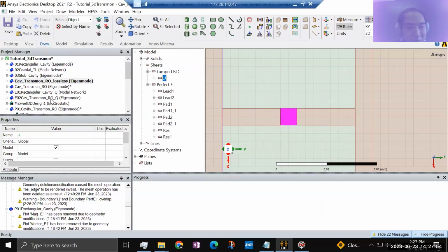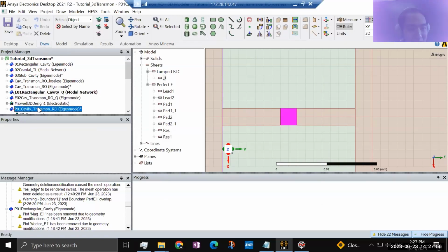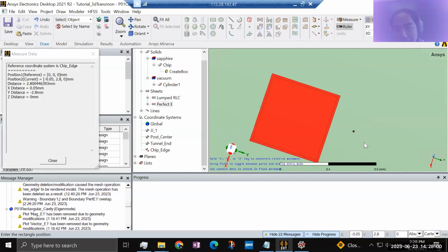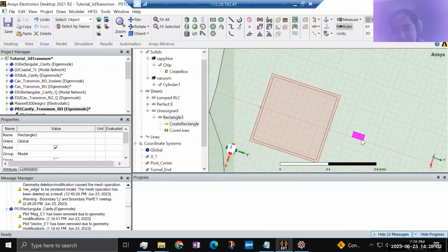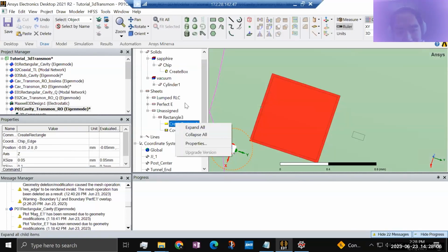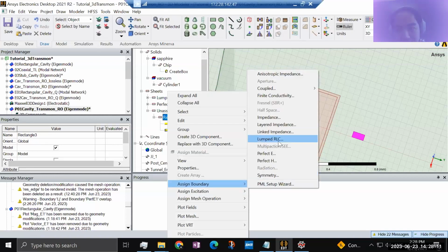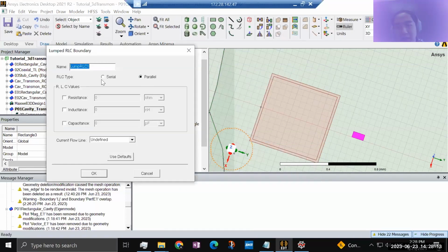Okay, I don't want to edit on this object. Maybe let's go to that practice object and make another sheet in here. Again, we want to parameterize the junction, etc. But the important point here is I want to show you the boundary condition of lumped RLC, where I call it Josephson junction. It's this element. And the junction has a boundary condition that is LJ.